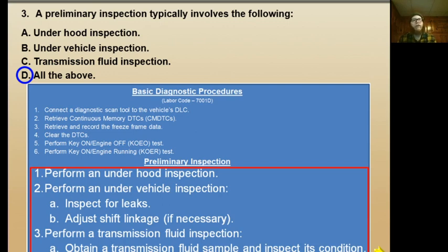And then use your sense of smell to see if the fluid smells burnt up. I guarantee you will know if the transmission is burnt up, because the fluid is so foul and so burnt smelling that it's not going to smell a little bit sweet like it should. No, it'll be very obvious. Oh my gosh, this is junk.